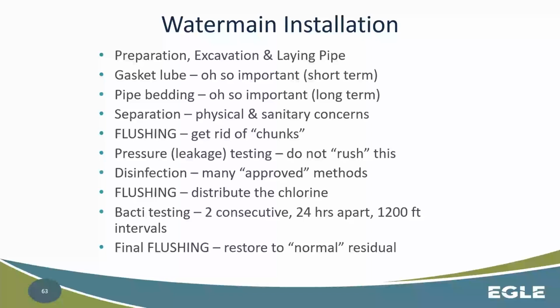Then you're doing your leakage and your pressure testing. Don't rush this portion. That's highly suggested because it's the long portion, and make sure that you're doing it right and that the water main was installed properly. If you're failing that test for whatever reason, it probably wasn't installed properly, or something went wrong along the way.